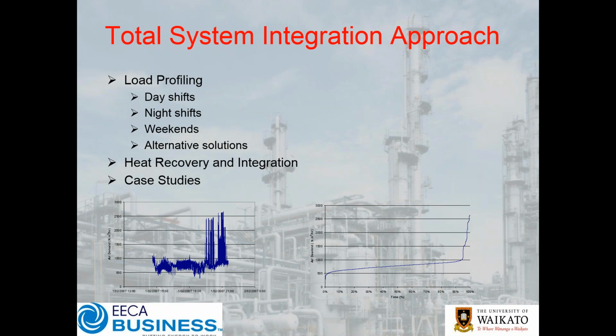Zero is an interesting target, because when you look at instrumentation and instrument air systems, you could potentially replace a whole lot of equipment with electrically actuated devices. But you start to use up quite large currents to actuate some things under some pressure, so it's a tricky one. I wouldn't rule it out of hand, but I think it would be quite a technical challenge for a number of industries.